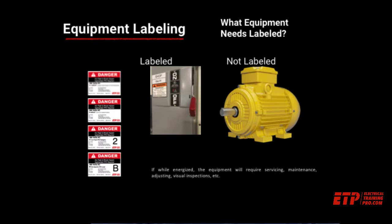What needs to be labeled? Well, equipment that while energized is going to require servicing or maintenance or adjusting or inspection. So what is that? Is it a motor, a three-phase motor connection box? No, we don't open those up while it's energized generally. We don't need to label those. But a disconnect, yeah, we have to open those while they're energized to verify they're not energized. We have to verify zero volts at the disconnects. And so when we open up that disconnect to verify it's turned off, we still have to treat it as if it's energized, so it gets a label.